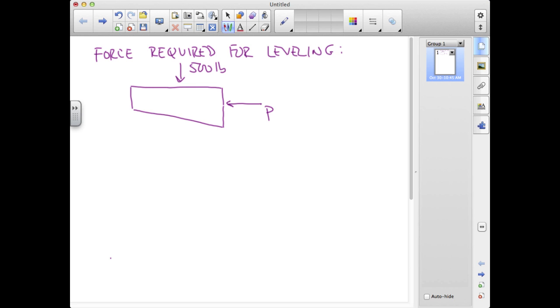So we're on the threshold of sliding if we're pushing this in. So this force up here is going to be the friction coefficient times 500 pounds. From the bottom, we don't yet know what this force Q will be. It's a normal force to that 6-degree incline, and we're also sliding on the bottom here, so I will also represent this friction force as mu times Q.